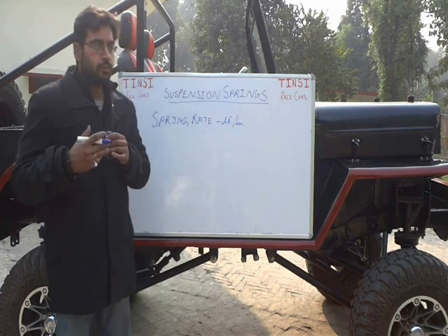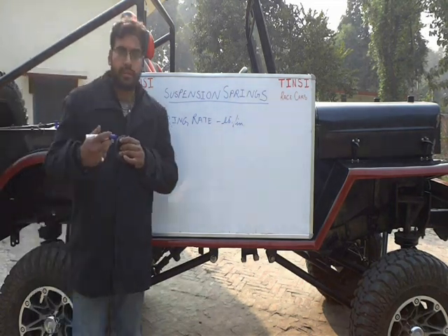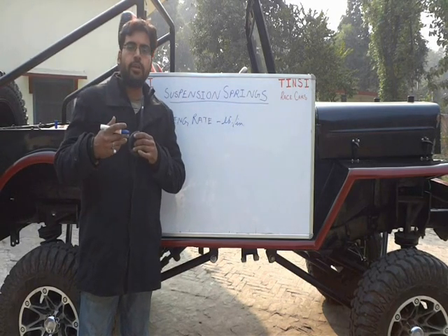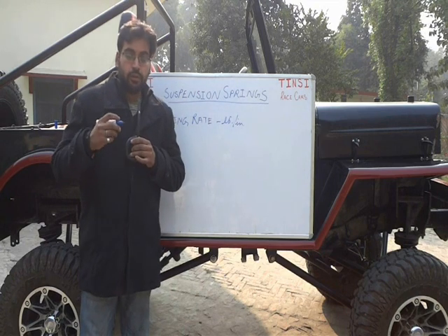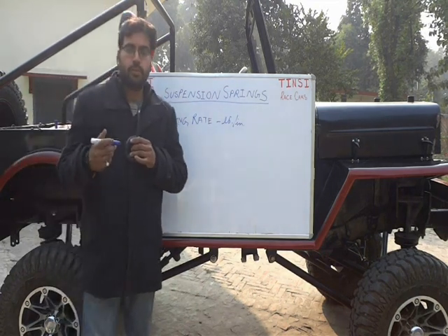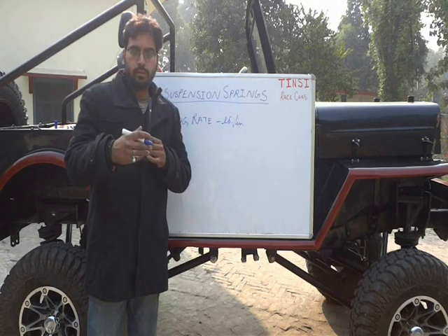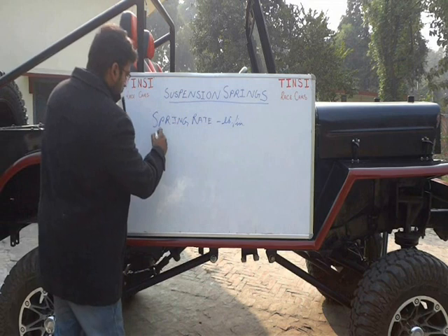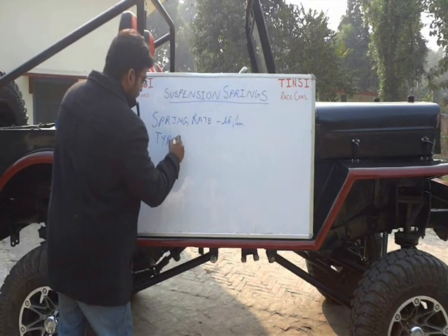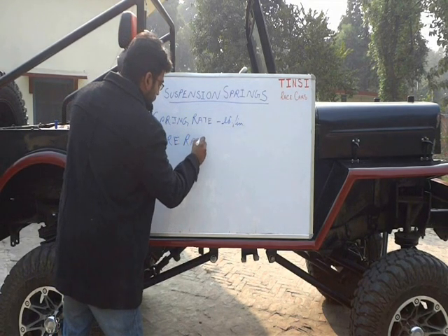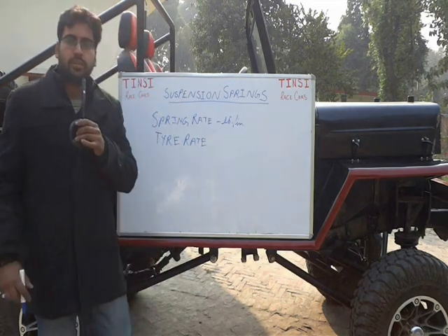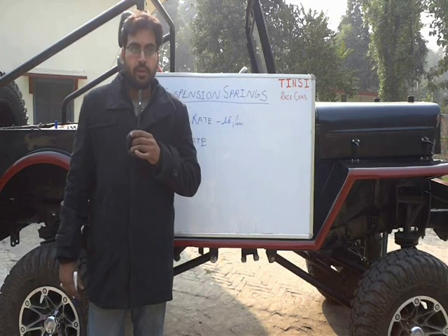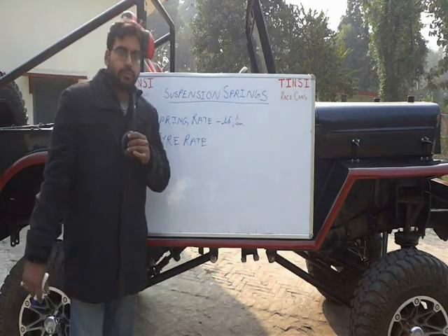Okay, next is the tyre rate. Tyre rate is the vertical force per unit vertical displacement, measured at the ground contact point of the tire. Okay, so why I'm telling you all this is because finally these things are going to help us in the designing of the springs. Okay, so we'll be just taking an overview of this.